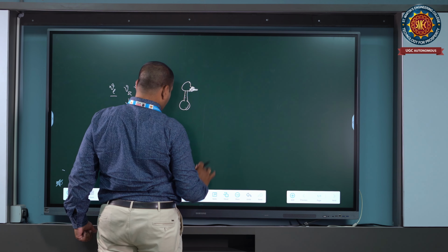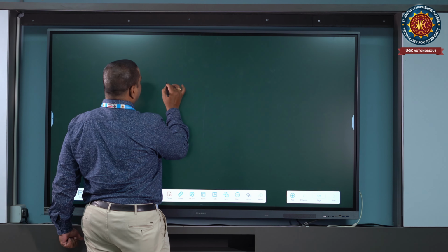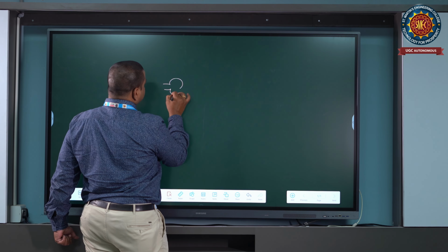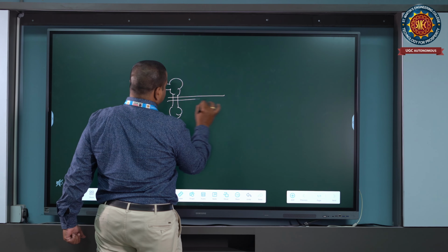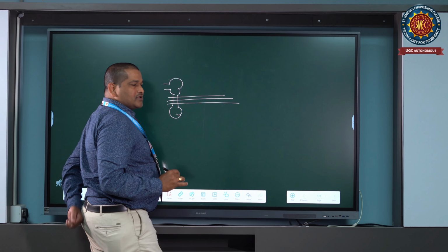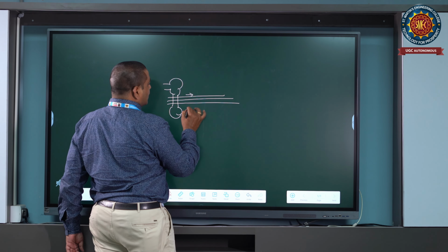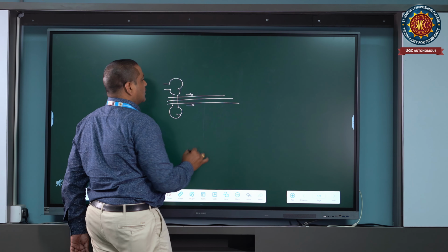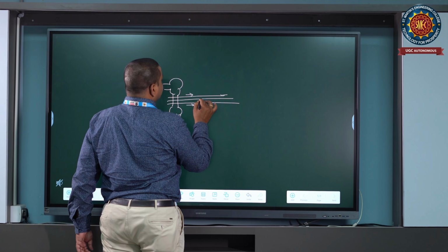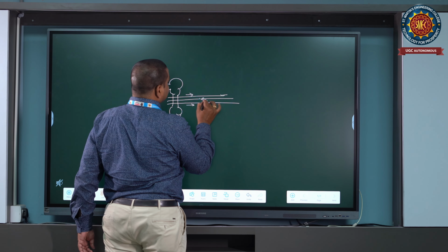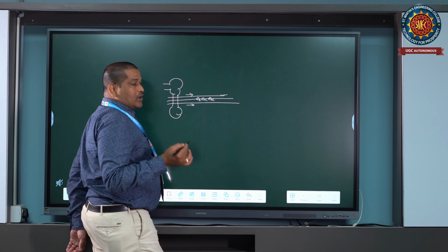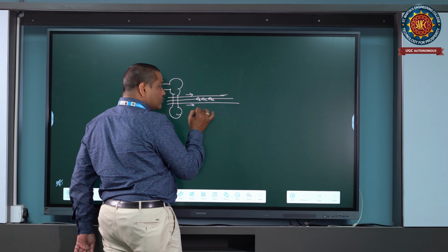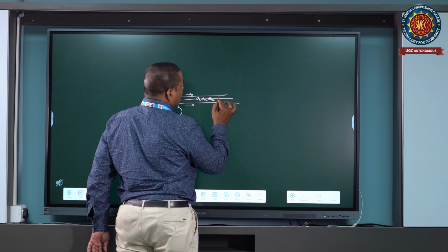here you can see this electron will be entering into the buncher cavity. This is called the buncher cavity, and they will be moving like this in a linear fashion, where electrons will be moving in the direction of the magnetic field. These electrons are called the reference electron, early electron, and late electron. These three electrons are moving with their own velocity. Now these three electrons are made to travel together, and they are made into a bunch.